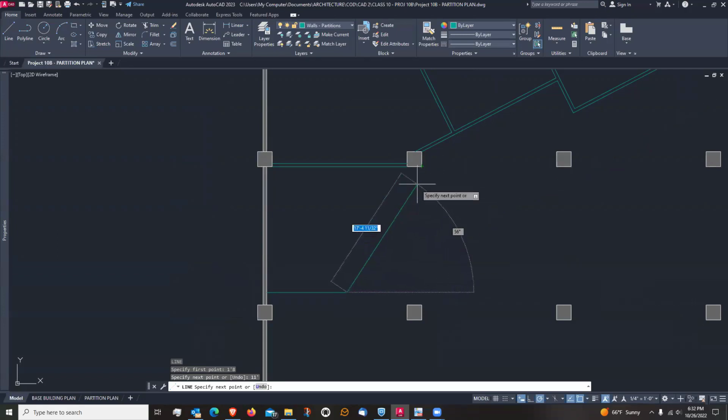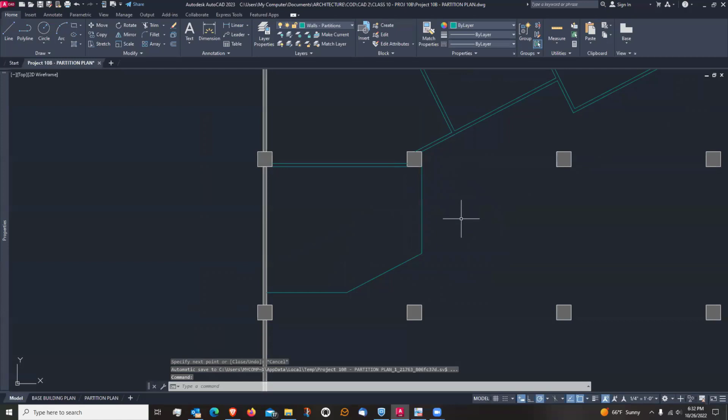And so what I did was I'm just hovering over here, coming down, and there. It's just snapped right on that 27-degree angle and the vertical there. So I'll just click and then just go right up. That's the nice thing about using O tracking. I can just hover over that corner and then it will find an inference where that intersection would be, that point right there, draw the line that long, and then I can go straight up.